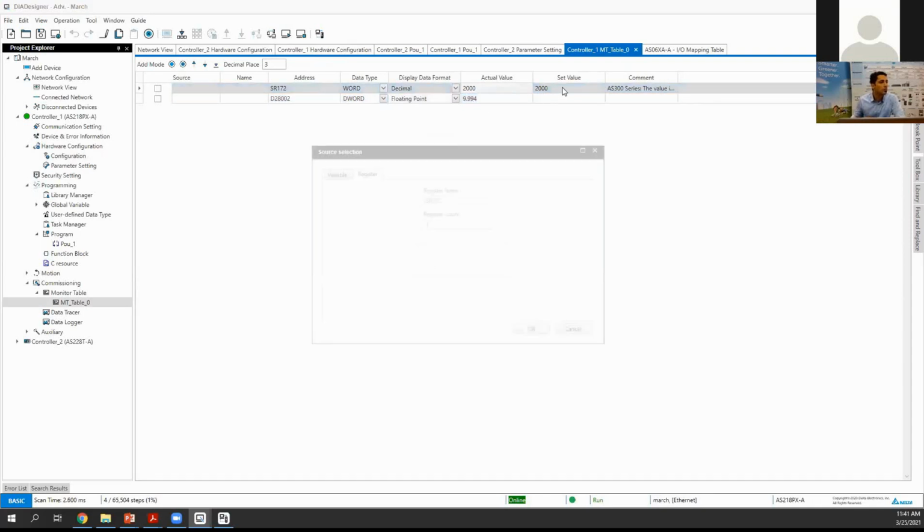For 5 volt, for instance, here you see directly 5 volt. So it makes it simple for us. The CPU directly converts it, so you don't need to use an additional instruction to scale it. Okay, so this is how analog works. Actually, it is quite simple.